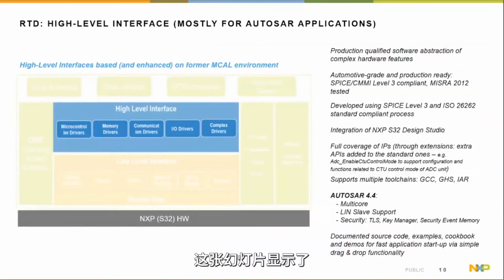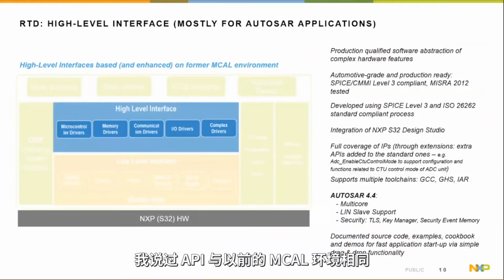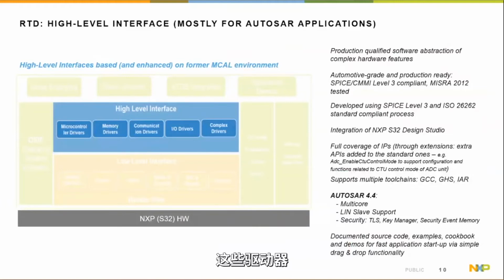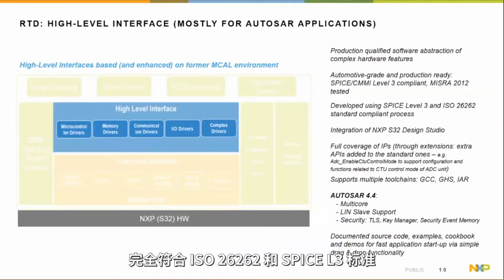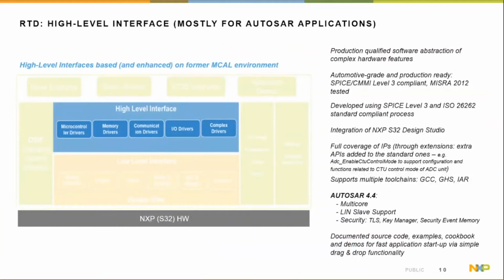And this just shows the high level interface for AUTOSAR use. It's driven by the standard. So as I said, the API is the same as the former MCAL environment, and the drivers are fully compliant with ISO 26262 and SPICE level 3.